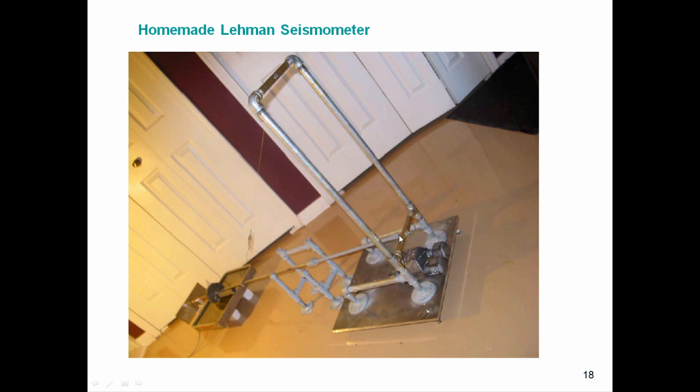There's a chisel blade here that butts up against a chrome polished bolt, and that's the pivot point. Then there's a wire rope cable that comes down from this frame with a little turnbuckle to adjust the tension. And then there's a ballast mass here that's partially submerged in a pan of oil to provide damping.